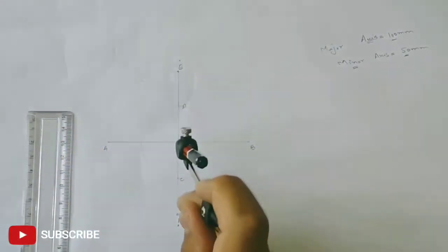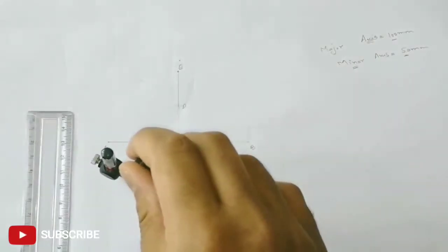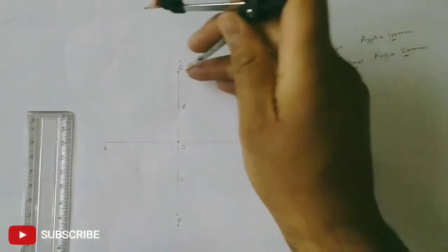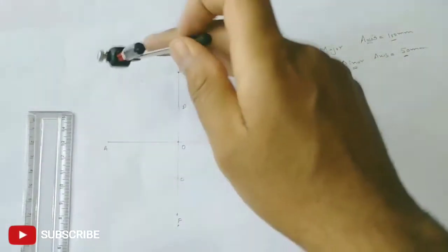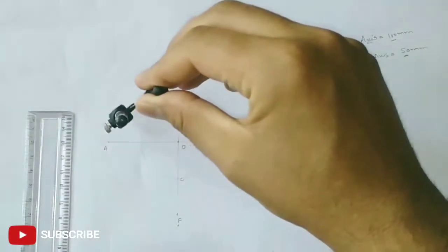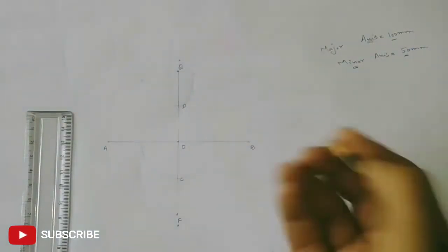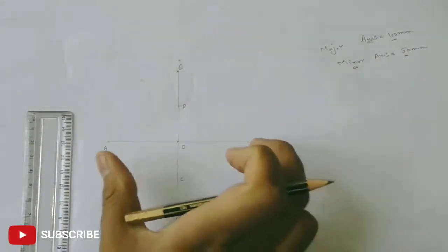Then I'll go to point F and draw an arc in this direction and in this direction. Then I go to the final point, point E, and draw an arc in this direction and in this direction. You can see that I have divided my circle whose diameter is equal to AB or FE into 12 equal parts.